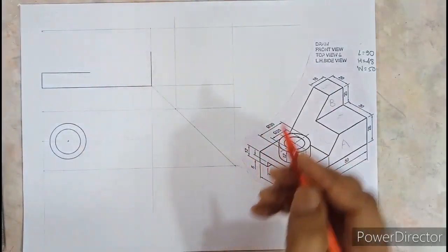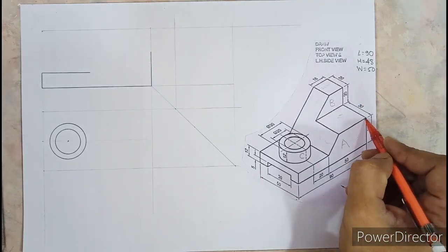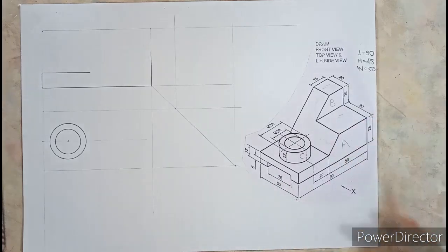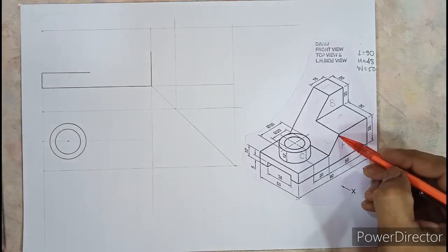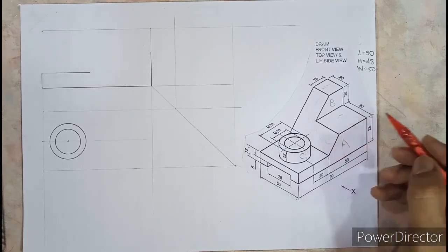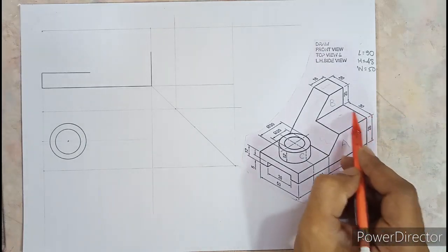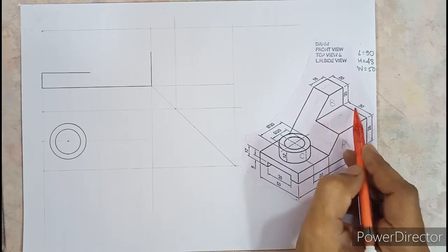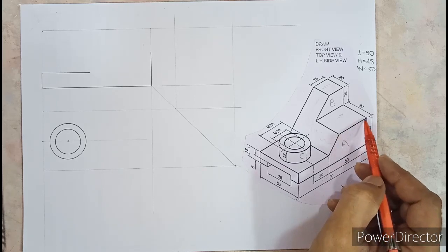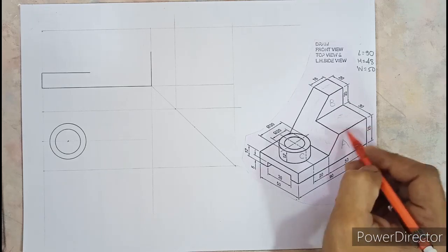Okay, object line. Now very important part, in the question this dimension is not specified. This length is not specified in the question. Neither this inclined edge length is specified, neither angle is specified. What students do is that they make suitable assumption. They say that this looks like a rectangle or looks like a square. So if this is 30, even this is 30. So that assumption is wrong because they have nowhere specified that this is a square. So it's a wrong assumption that this is 30.